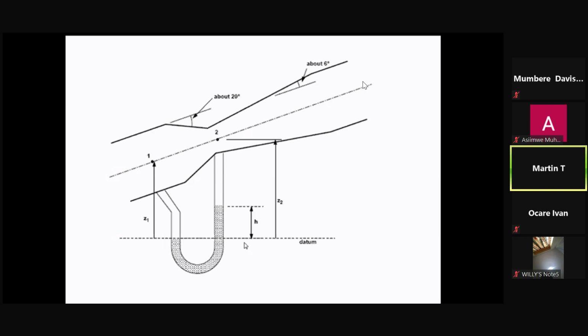The reason we have the manometric fluid rising in the limb on the right-hand side is because there is a pressure drop, so pressure at 2 is less than pressure at 1. But even if you sketch it the other way and work it out from first principles, you will still get to the same conclusion.